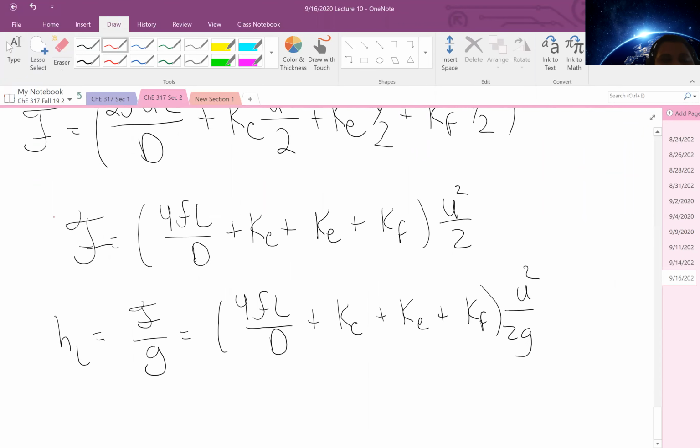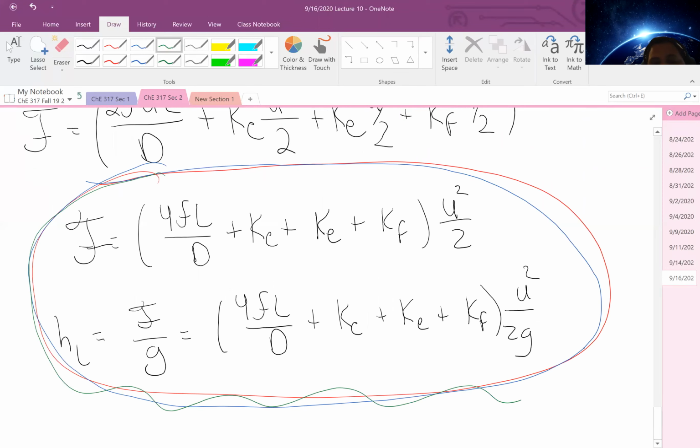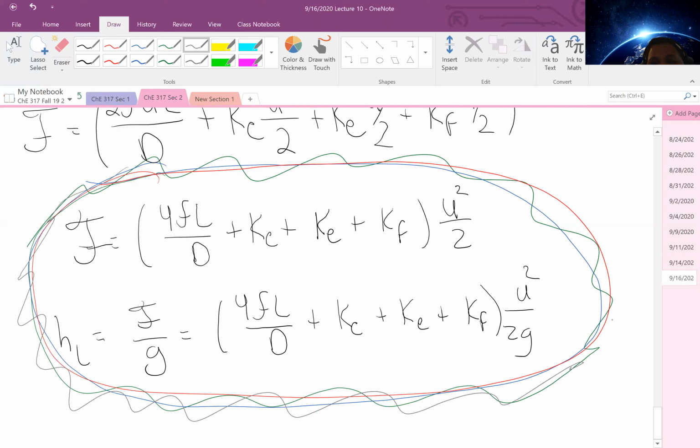So these become extremely important expressions for determining our frictional dissipation in our fluid flow systems, which denotes what we expect due to skin friction, which is more often than not going to be the most predominant source of frictional dissipation, as well as any expansion losses, contraction losses, and fittings within our system.